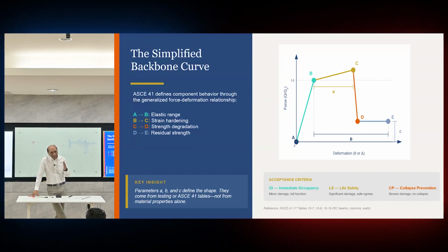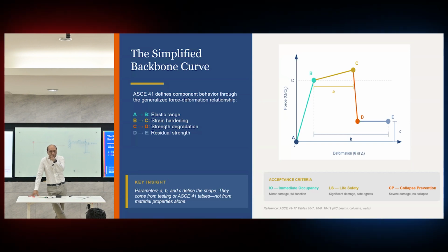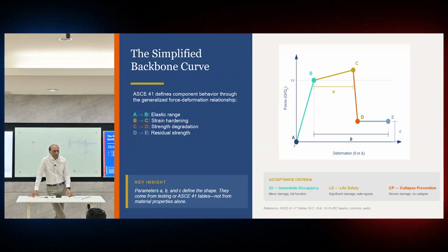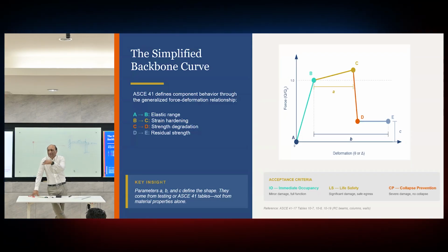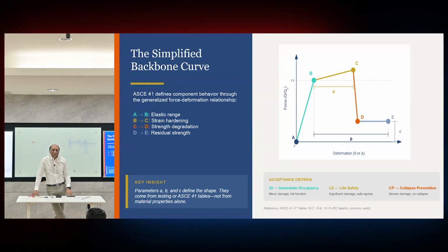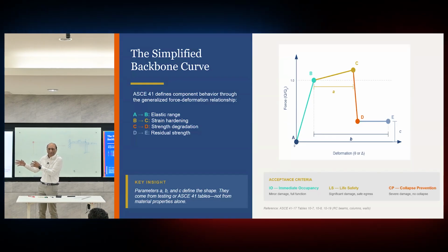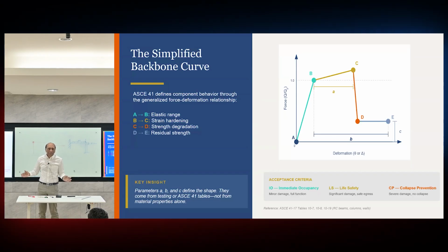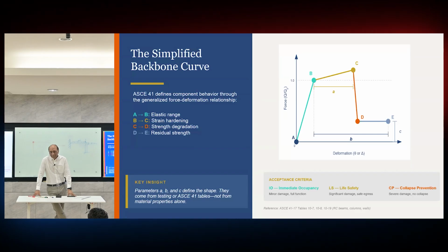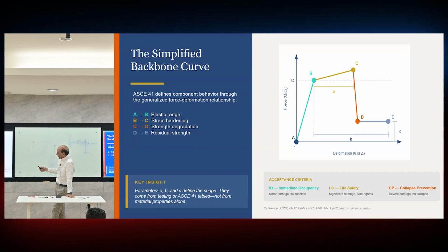When you define the material, when you define the moment rotation curve or moment curvature curve, you input a curve like this, and on that, you specify those performance points. The output curve will be similar. Depending upon where it has reached, you can then check, because input is based on material and section, and output is based on structure response. But the plot is the same. The limits are the same. That's why it's easy to check the two things together.